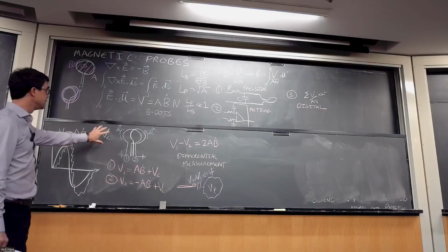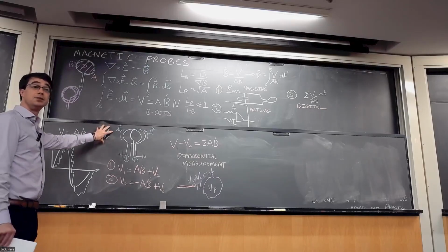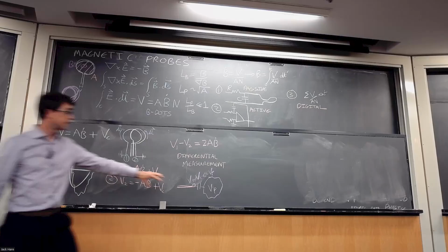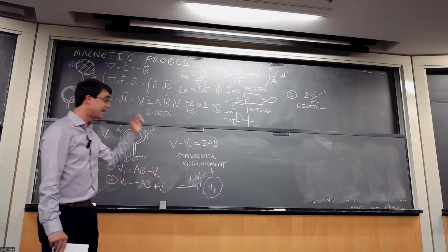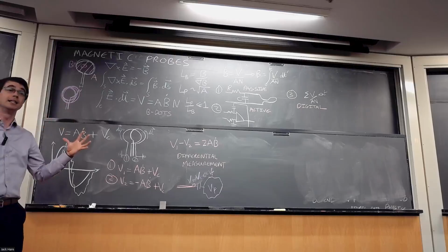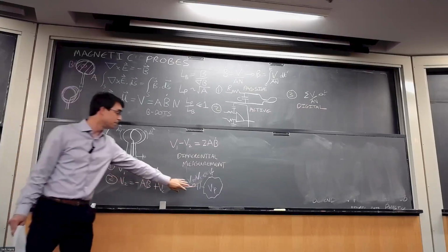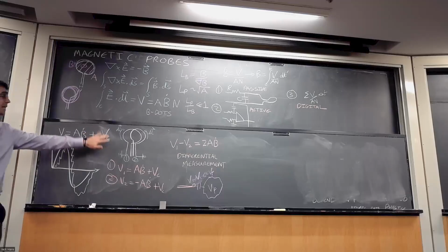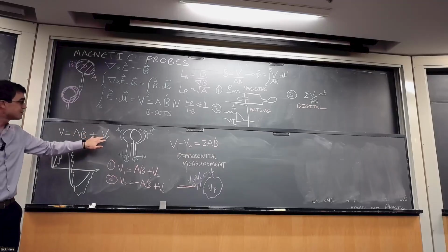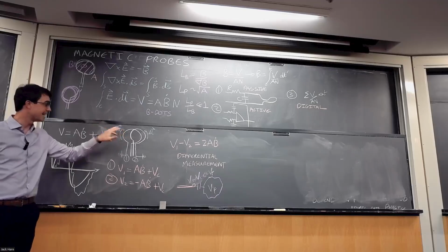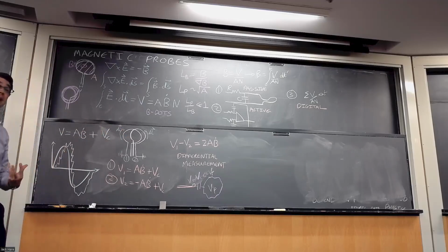Yeah, so the idea here is this could be due to anything. This is due to some high voltage being present somewhere in your system. It could be a capacitor bank discharging, or it could be a kilo-electron-volt plasma. But the fact is that any conductor and any other conductor have a capacitance between them, always. There is an ability to induce some potential on one conductor from the other. And so all I'm saying is, if you have some stray potential, it will couple with the same sign to these two probes. But because they're oppositely wound, we'll be able to cancel out that same sign potential.